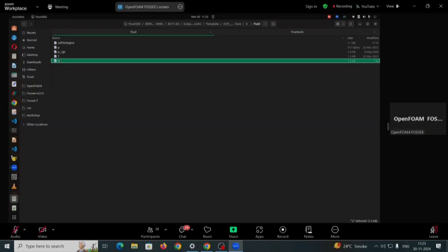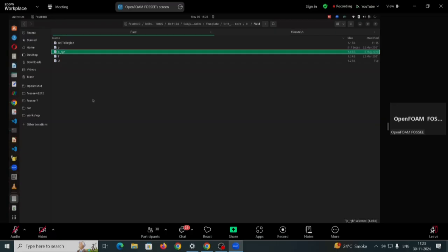So, for ease of solving, generally from the total pressure, the rho gh term, that is the hydrostatic component, is subtracted, and you have the PRGH pressure. So, generally for multi-phase cases and for heat transfer solvers that take into account the buoyancy effects, PRGH pressure is solved.